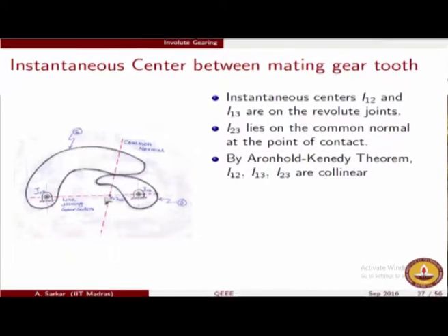So, this angle between the force transmission, as occurring in a true gear pair between a gear tooth and the point C, and the common tangent between the two pitch circles is called phi, the pressure angle. So, phi is called the pressure angle. Usually it is about 20 degrees as per standards, but that is besides the point.